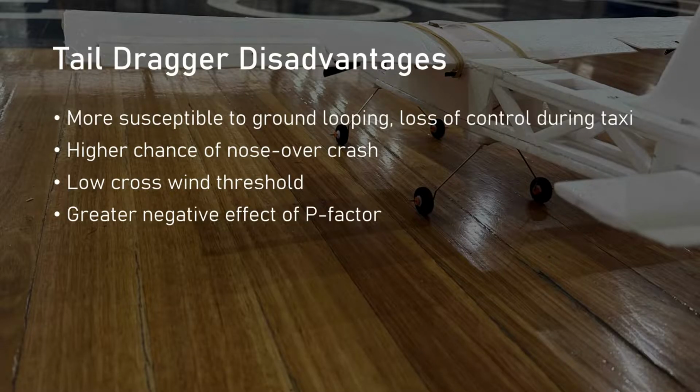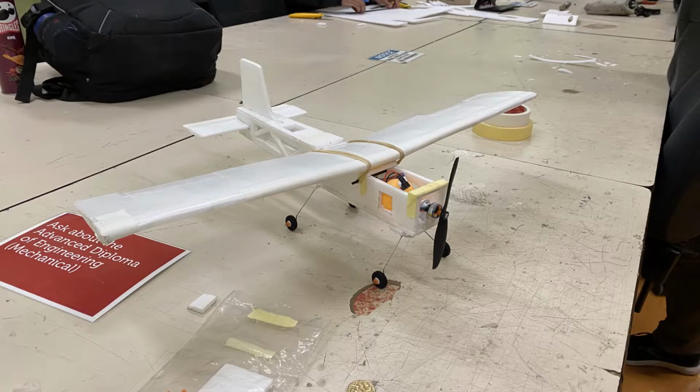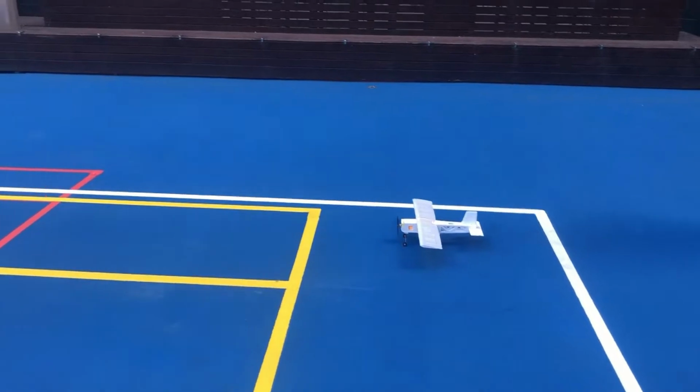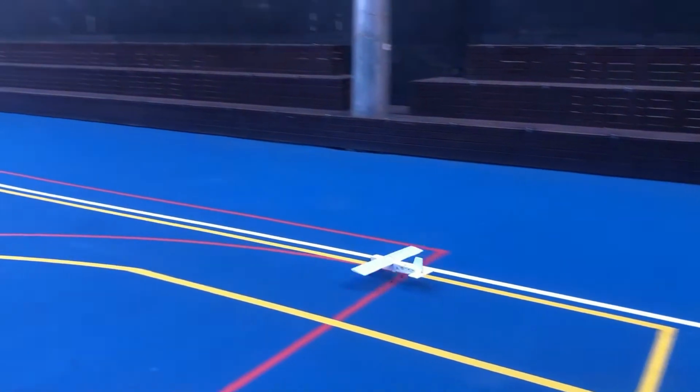Our ground control issues likely came from our absence of a rudder, not being able to control the inherent nature of tail-dragging aircraft. After some additional research, it was found that tail draggers commonly have poor ground control characteristics. This meant that they required a rudder to steer the rear wheel. As we already needed to save weight, we didn't add one. We instead decided to change our landing gear configurations to one that was more stable and easier to taxi.